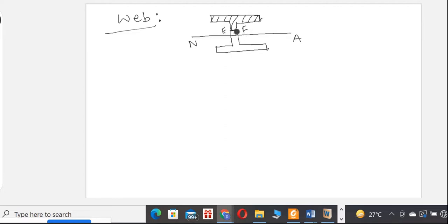That is the definition: for the EF level which is y distance away from the neutral axis, we have to consider the total area above the EF layer. So now we have to use this formula and replace the components and then rewrite the expression.